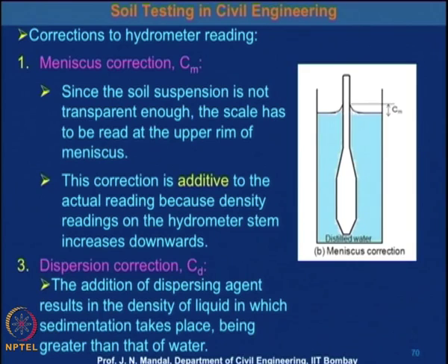Now, there is a dispersion correction, designated as Cd, because the addition of the dispersing agent results in the density of the liquid in which sedimentation takes place being greater than that of water. So, this dispersion correction is also needed.